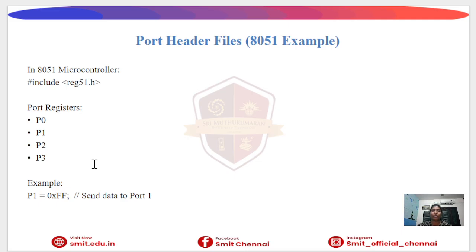Next one is the port header file. What is meant by port header file? In the 8051 microcontroller, we include reg51.h. This is the header file that defines the port registers. What are the port registers here? P0, P1, P2 and P3.